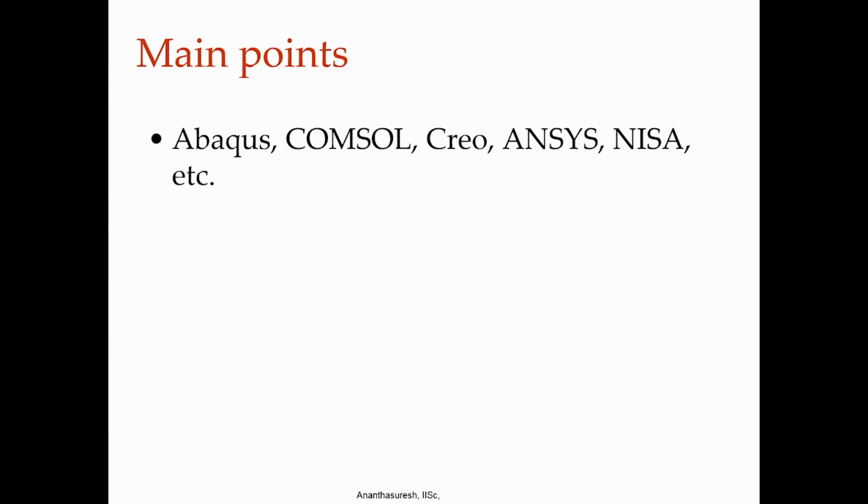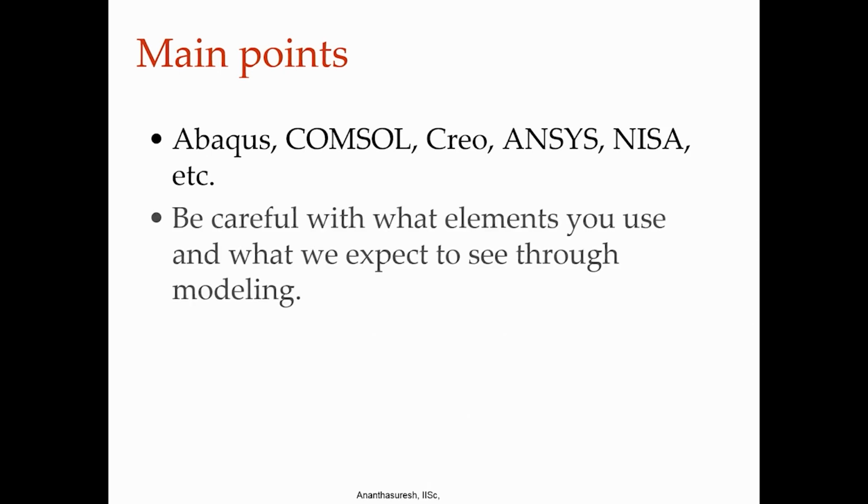So let us just summarize what we have discussed. We can use any finite element software, it does not matter which one you use, whatever you are comfortable with you can use that. The results that I have shown were done with Abaqus, COMSOL, Creo, and some with ANSYS and NISA. These are the ones that we use in our group, but just about anything is fine. We have to pay attention to what kind of elements you use, and make sure that you check the option of geometric nonlinearity. If contact is there, you have to define contact elements and do the kinds of things that we saw in two examples today.